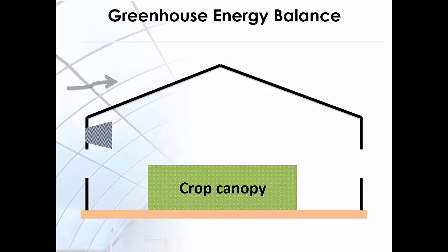When we consider energy and mass balance for the greenhouse system, we need to consider the law of conservation for any given volume. In this case, the greenhouse was our control volume. In order to establish a general rule, we first considered energy, then we easily converted that into discussions for the mass flows and mass balances.